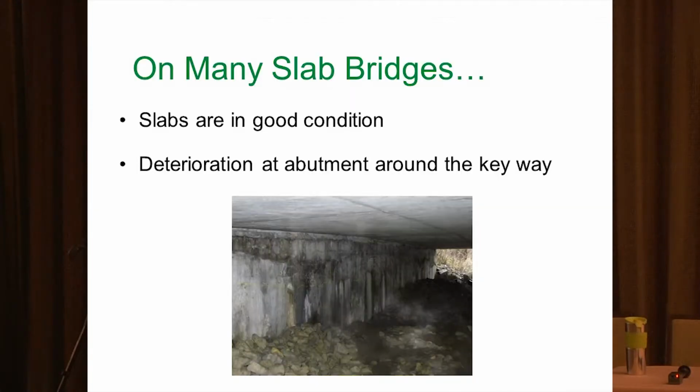This same thing can occur in other areas on bridges too. We've done over 35, I believe, repairs for Ohio DOT on some of their slab bridges. And on slab bridges, one of the more difficult areas, as everybody here realizes on any bridge, is certainly the expansion joints. On these bridges, they're having problems on the expansion joints. Salt-laden water was going down to the abutments below, causing spalling.